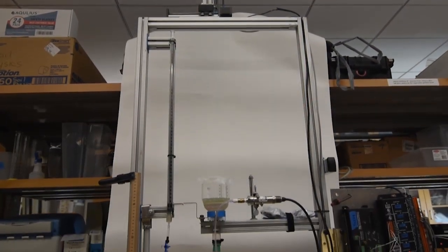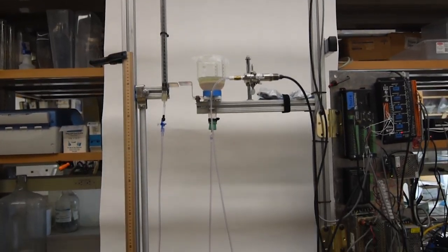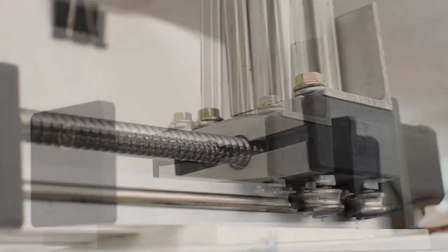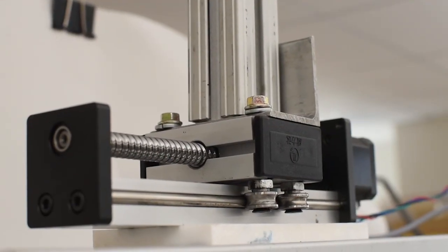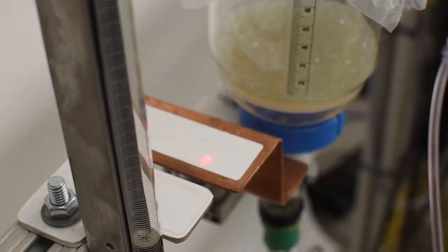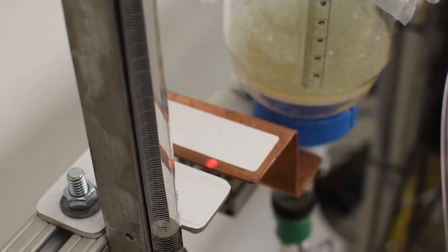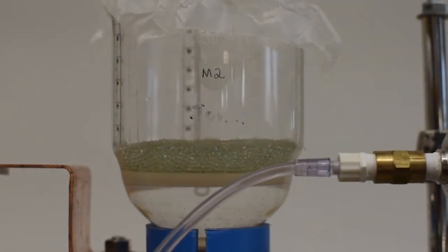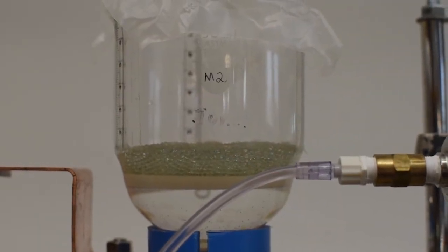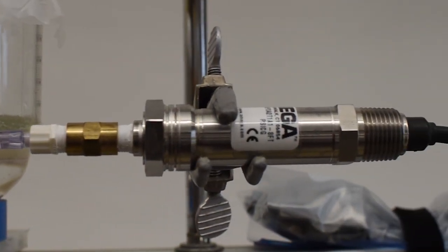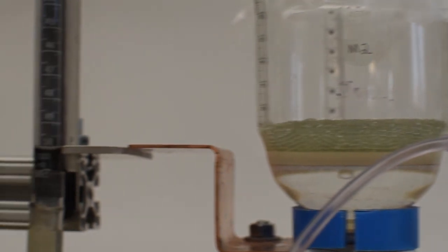This is our automated system that employs the hanging water column method. A laser distance sensor is mounted on top of a linear actuator, and it moves parallel to measure two vertical positions, which are the burette reference level and the funnel reference level. A Buchner funnel with ceramic plate holds the sample by maintaining hydraulic contact with a pressure transducer and a burette through the tubing.